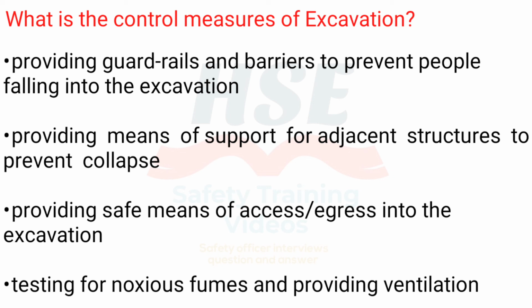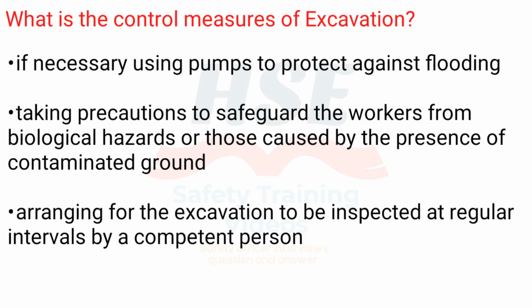Providing guardrails and barriers to prevent people falling into the excavation. Providing means of support for adjacent structures to prevent collapse. Providing safe means of access, egress into the excavation. Testing for noxious fumes and providing ventilation. If necessary, using pumps to protect against flooding.